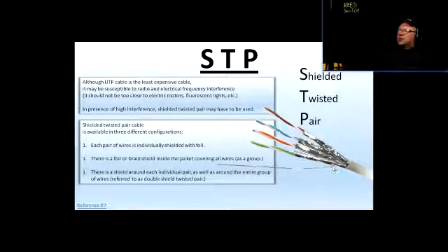There are certain ways of installing, they're using different, more expensive jacks. Of course, the cable is more expensive, way more expensive, but sometimes you have to use shielded pair cables. Where would you mostly use those STP shielded pair cables? In the industrial environment. So if you have a building that is basically an office building, and you just run the wires from the LAN room to the desktop locations to accommodate the computers and whatnot, then by all means, for the most part, you get away with the unshielded twisted pair, which is UTP.